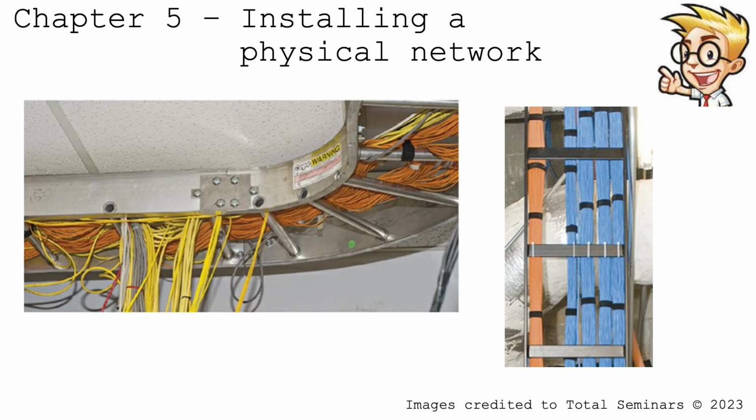Here's an example of what you don't do with cable trays. This cable tray is a mess. If I need to pull a cable or if one's broken and I need to figure it out, it's going to take me a long time and I'm going to have to pull a bunch of cables and see which one wiggles and moves, and that's going to be a headache.